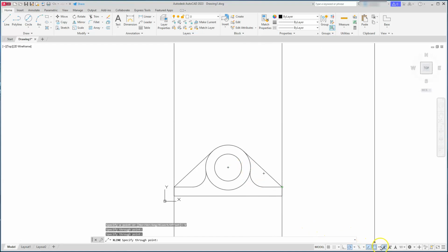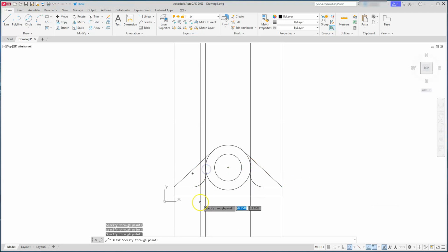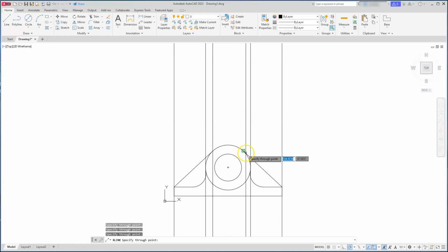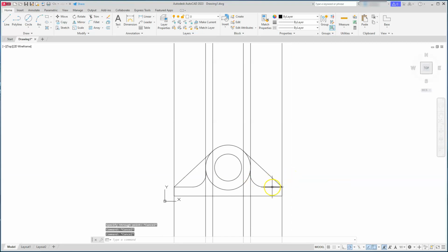So what I'm going to do is I'll turn the quadrants on by selecting the fly up. And then I'll go and find quadrant. And that's going to allow me to click the quadrant here and here. And I'm also going to use these tangent points. So right where it endpoints here and here, I'll go ahead and create and save those parts. There are a couple of circles that are running through here, but I'll locate those on the top view.